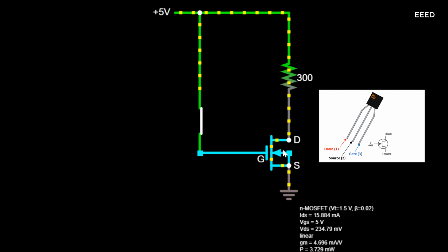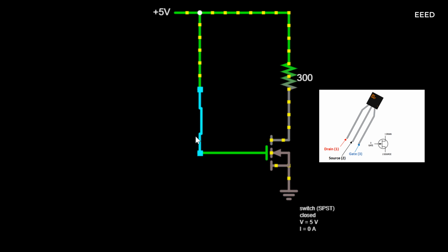of the N-type channel. When no voltage is applied to the gate of an N-channel JFET, current flows freely through the central N-channel. This is why JFETs are referred to as normally on devices. Without any voltage applied to the gate terminal of the transistor, they conduct current across the drain-source region.